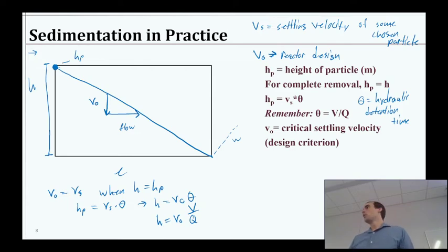It turns out we have a way to simplify this further, because we know our volume relates to the height of the reactor. Since we are designing this based on the height of the reactor, that's kind of our design scheme here, we're going to say this is equal to V naught times length times width times height, which is going to be our volume for a rectangular system, right?